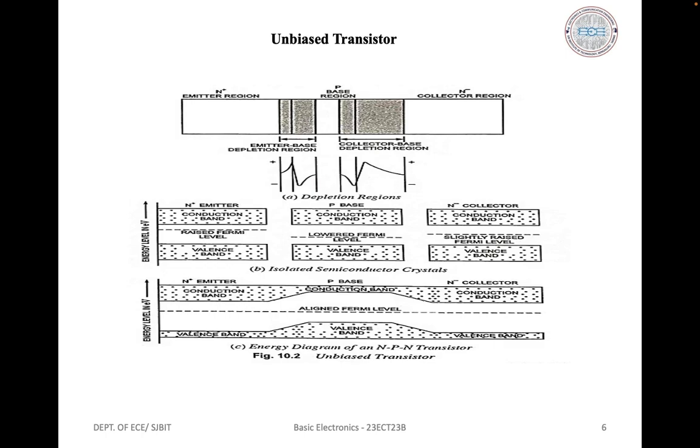The reverse bias at the collector base junction causes the collector base depletion region to penetrate deeper into the base than when the junction is unbiased. The electrons crossing from the emitter to the base arrive quite close to the large positive electric field at the collector base depletion region. Because electrons have a negative charge, they are drawn across the collector base junction. By this bias voltage, they are said to be collected.